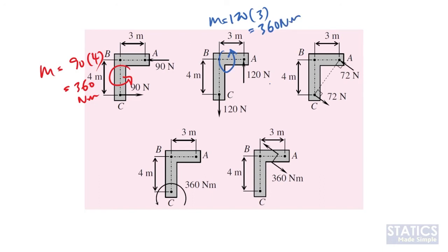So both of these are the same amount of moment, but given through different magnitudes of force acting along different directions as well. Okay, the same goes here. If we want to extend the example further, we have 3, 4, this is 90 degrees, so this line is 5.